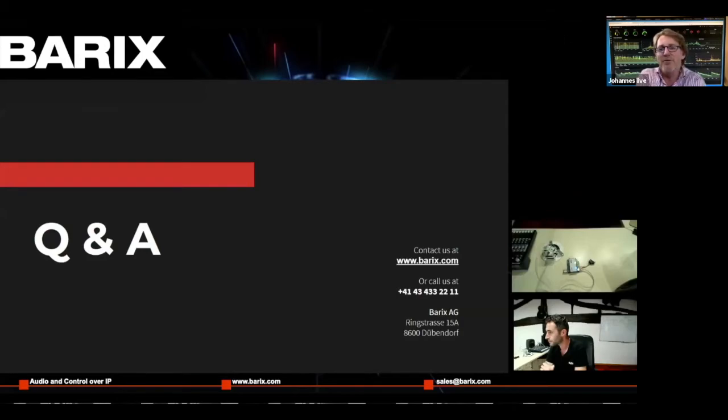Something else I want to know is about my power needs, right? So I need a so-called current sensor. This one is an intelligent current sensor, 3-phase. In Europe, we have 3 phases. In the US, you have split phases eventually. So you will need something which measures the current going in and eventually out from your installation, and provide that information to the Barionet. This thing has a Modbus interface here, a Modbus RS-485.